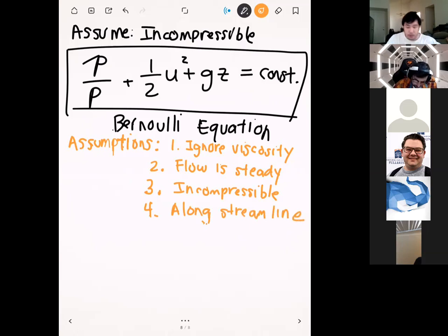And so if you're going to apply the Bernoulli equation, you can't go across the flow. Like you can't go from one bank of the Mississippi River to the other side and apply Bernoulli that way, because that's not where the fluid flows. The only way that you can apply Bernoulli is in the same direction as the Mississippi River. So you can only go down the river, not across it. So you have to follow basically the path of the flow when you're applying Bernoulli. Okay.